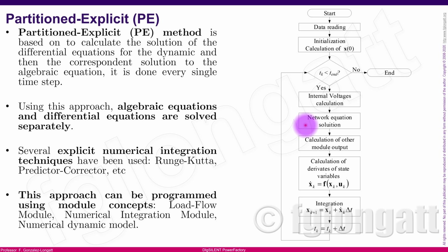What I'm trying to say is that the partition explicit method is basically the solution of the differential algebraic equations, where you use explicit numerical integration to solve the differential equations, and then you use any algorithm to solve the nonlinear algebraic equations, okay? Typically, every single power system analysis software has very strong routines for explicit numerical integration, like Runge-Kutta, predictor correctors, and so on. In many of the commercial software available in the market, the full details of the explicit numerical integration are an industrial secret, and it's something similar for the implementation of the algebraic solutions, okay?